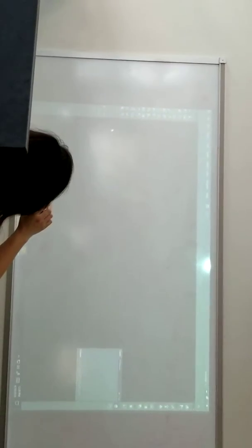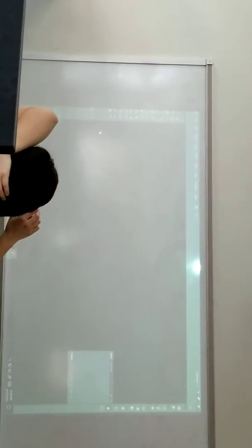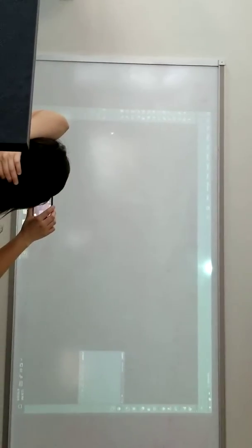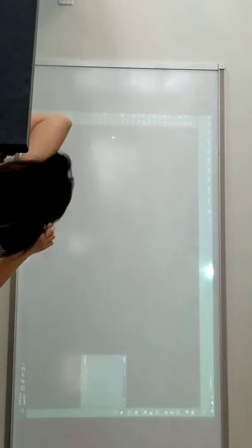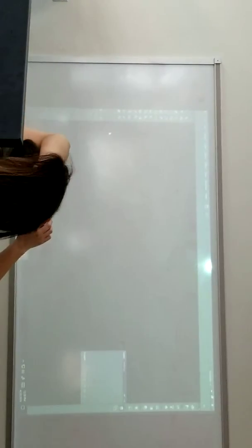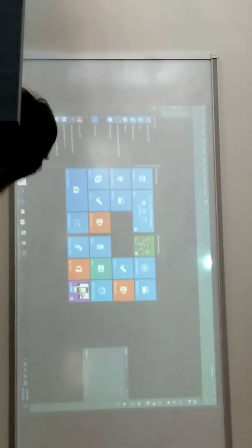You know, I want to trim these two lines. I think AutoCAD can do something like trim. So let me just type trim. Oh, there's trim. Now I can do that command, right? Oh, you know what? I want to join these lines. I think if I start typing in join, oh, there's join, so I can join the lines. You can logically teach yourself how to do more in this software. Are you with me? Get it? Okay. It is better than Illustrator. Why? This is Illustrator. Let me open up AutoCAD while I'm talking. Why is it better than Illustrator?